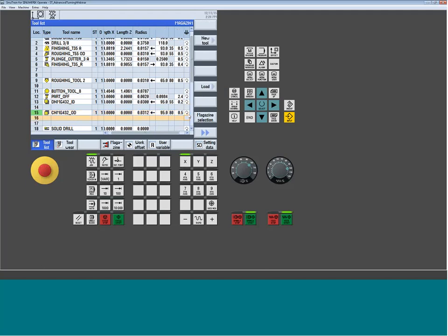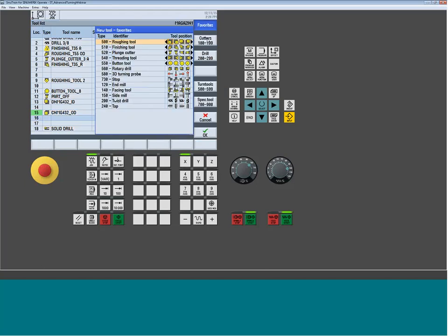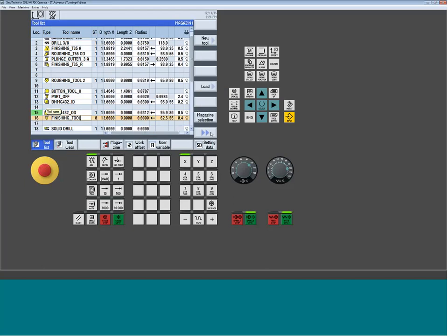And just to show you quickly, like if we were doing a neutral tool, like that 35-degree neutral we just showed before, I'd probably pick a finish because the insert picture looks a little bit more like it. But now I got to remember to expand over and pick the appropriate orientation. So I pick the neutral tool. I say OK. I'm going to call this, and maybe it's a VNMG, pretty common, like a 331. And we'll say that this is an OD tool as well. And maybe because there could be a handed tool, the same geometry, I'll even tell it it's a neutral tool. Okay.